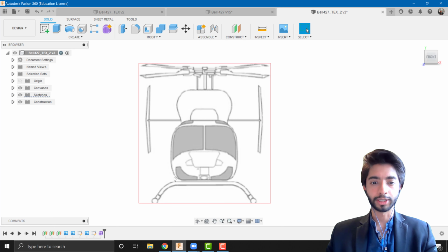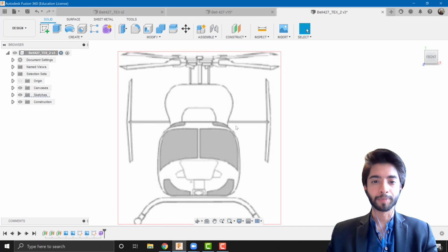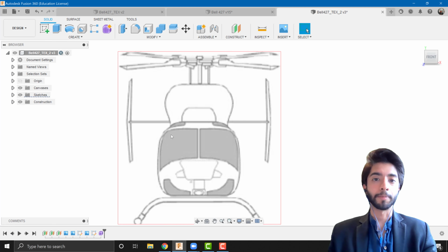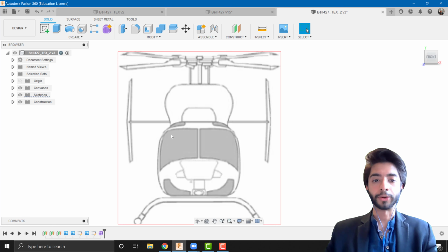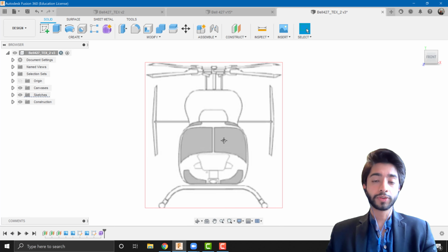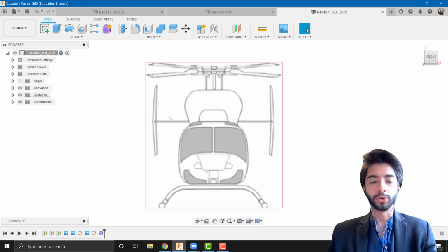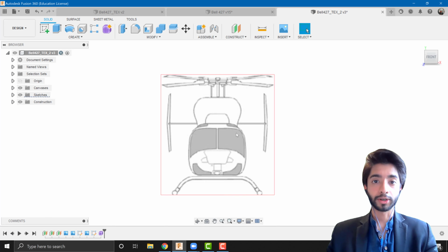So the bottom section is more of a square/rectangular cross-section with a little bit of rounded edges, and the top has a completely different cross-section. In general, it's a good idea that if the structure of the body has a different cross-section, to split them differently altogether. If you've seen my aircraft video series, you already know that I use the T-Spline way of doing things. So we enter the T-Spline workspace, and then we use a preset, then we extrude that and shape it accordingly along the span of the length of the fuselage. Great, so let's start doing that right away.